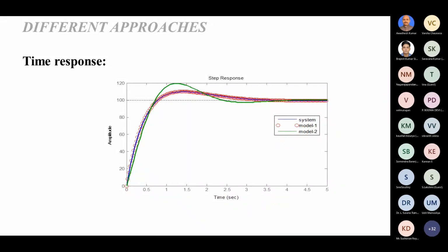So sometimes if a Padé approximation is getting a better overall time response approximation, we should not discard it on the concept that Markov parameters may not be matched. In certain examples, matching of Markov parameters automatically takes place, so that people can go ahead with matching only time moments.